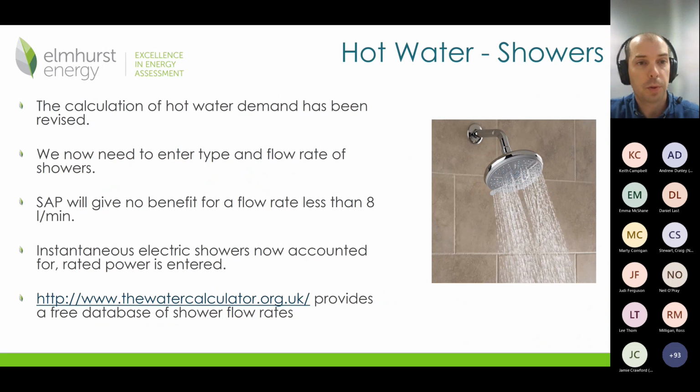We now have to enter showers, because the calculation of hot water demand under the bonnet of SAP has changed quite a bit. So we now need to enter showers and their flow rate, and also instantaneous showers as well, which were never accounted for before.